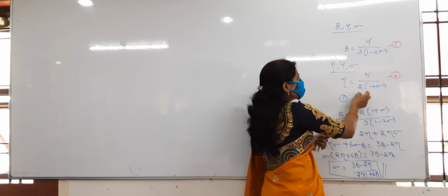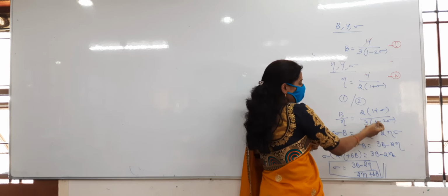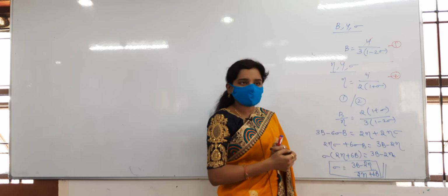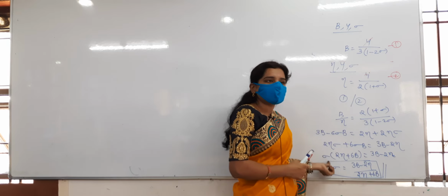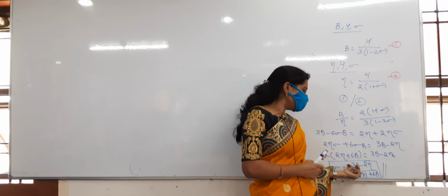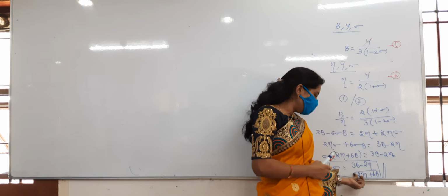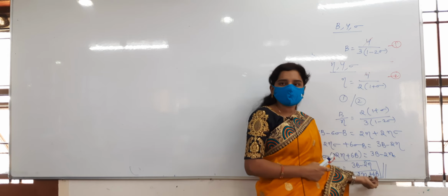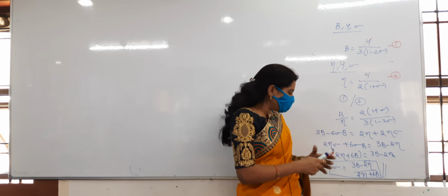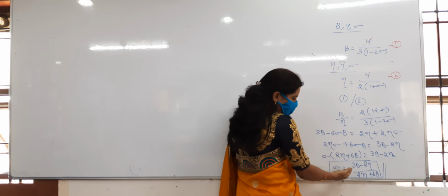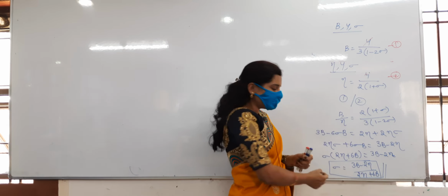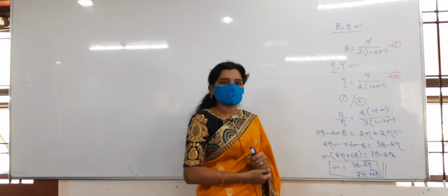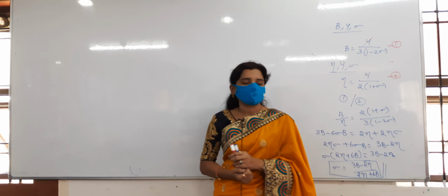After that this will go up and this will come down, so whenever you cross multiply them, you have to take sigma as common and then get the sigma value. Sigma is equal to 3B minus 2 eta by 2 eta plus 6B. This is what you will get. This one is also easy to remember: 3B minus 2 eta divided by 2 eta is coming as it is. For this again you get 2 times here, that is 6B. That is about the sigma formula.